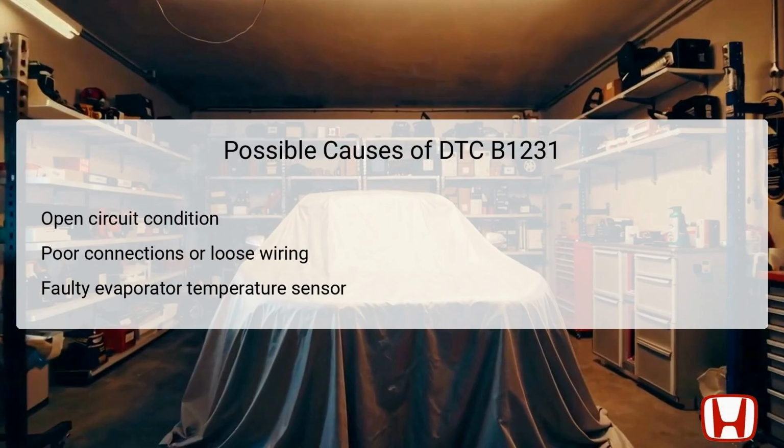Furthermore, it's also possible for the evaporator temperature sensor itself to be faulty, which would prevent it from sending accurate temperature readings to the climate control system. Each of these causes needs to be systematically addressed to restore proper functionality.